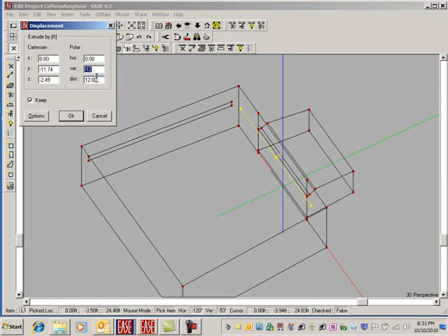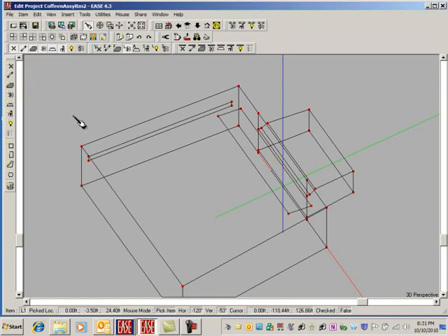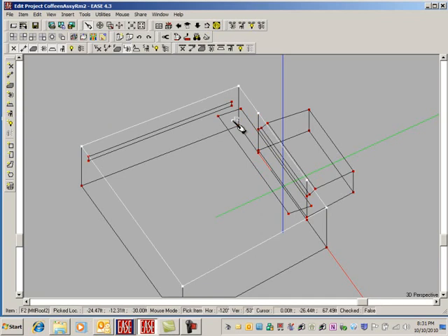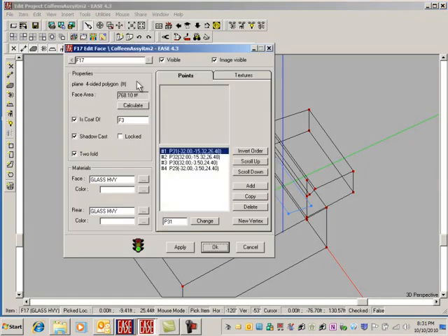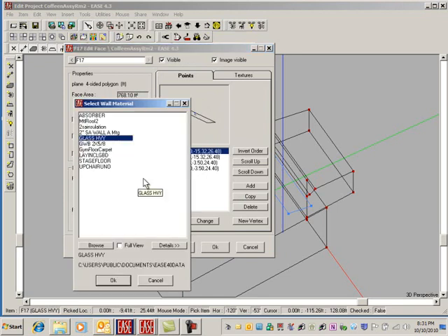Now we'll do the same thing for the back three. Locate a vertex someplace. X again is minus 32. And the y value this time is 27, 31 and a half. 14 feet plus 13 feet, 27 feet. 31 and a half feet, so minus 31.5, and z is 3 feet down from 30 feet, so it's 27 feet in the air. Say okay.